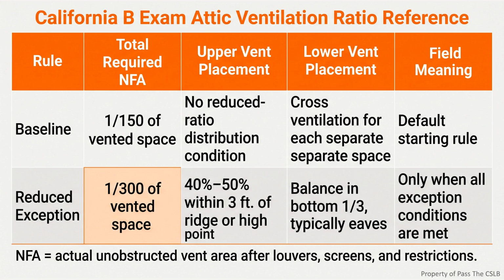A roof can have soffit vents, ridge vents, and a clean inspection photo, yet still have a ventilation failure. The reason is simple. A vent is only an opening. Ventilation is a continuous route. I want you to picture three connected parts. Intake air enters low at the eaves. That air travels through an open channel beneath the roof sheathing. It leaves through exhaust vents high in the attic. If insulation, blocking, or a crush baffle closes the middle of that route, the vents at both ends cannot do the job shown on the plans.